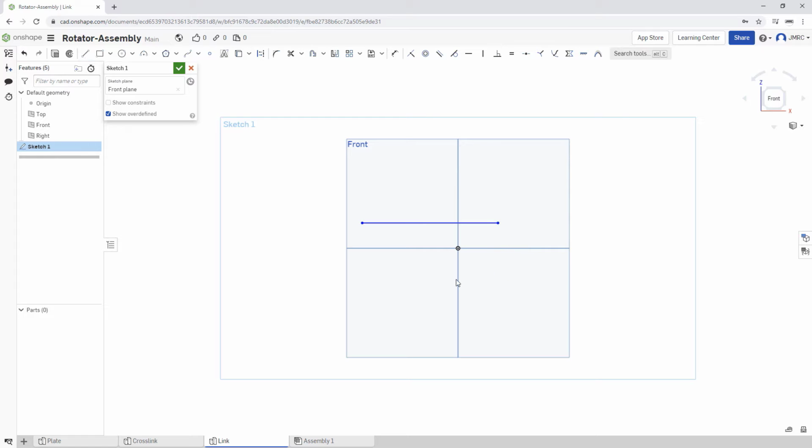Left click here, hitting escape. Hit L once more for align. Left click here and left click. Hitting escape. Next, let's grab our arc, specifically our 3-point arc. I'm going to hit A, which is the shortcut for that. Dropping the first point at this endpoint, selecting this endpoint, moving to the right. So notice the inferred tangent constraint, left click, create another arc, starting from this endpoint,